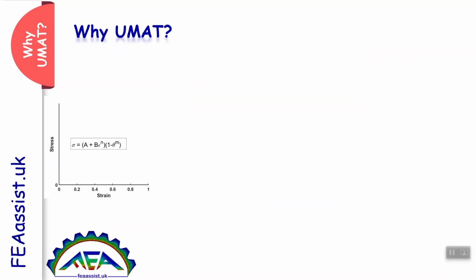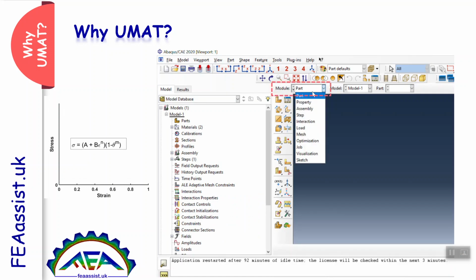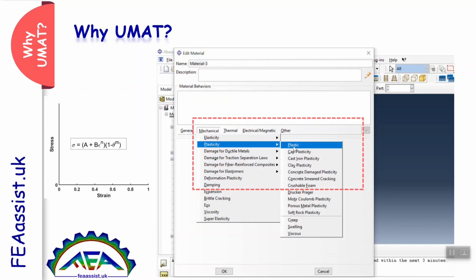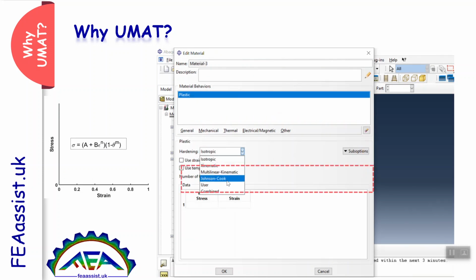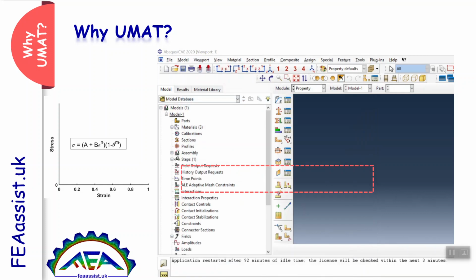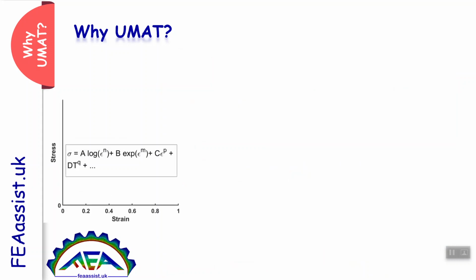Again, if you have a well-known constitutive equation included in Abaqus, you can go to the property, define a material, and instead of entering the points, you can define the behavior and enter the parameters and constants of your model. Here it is the Johnson-Cook model. It is a more precise solution because you have an equation for all your points.